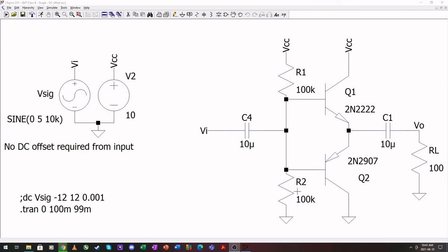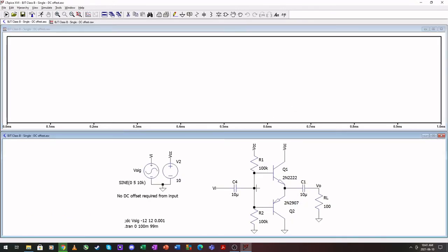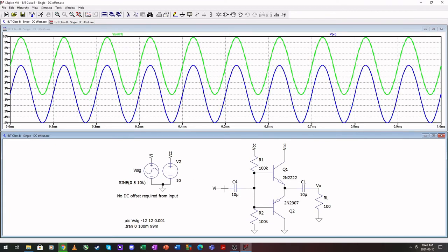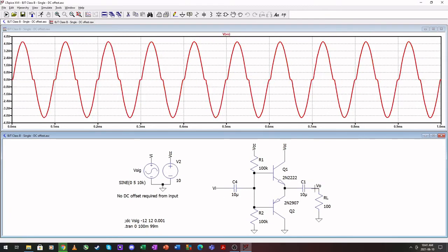I just put a little something together. If you don't want to add a DC offset to the input necessarily, you can do DC blocking on input and output and just put two big resistors here of equivalent size. That will do your DC offset for you. Add the 5 volts and the output result will be very similar.